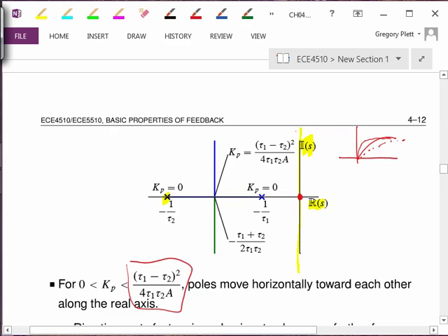That's a complex set of conjugate numbers. So if I turn up the gain enough, this pole has moved to some point up here, and this pole has moved to some point right down there. And the response that we get from that is a little bit mixed. The omega n is, again, this distance from the origin here, so that's a little bit larger than when the poles were right at that junction point.